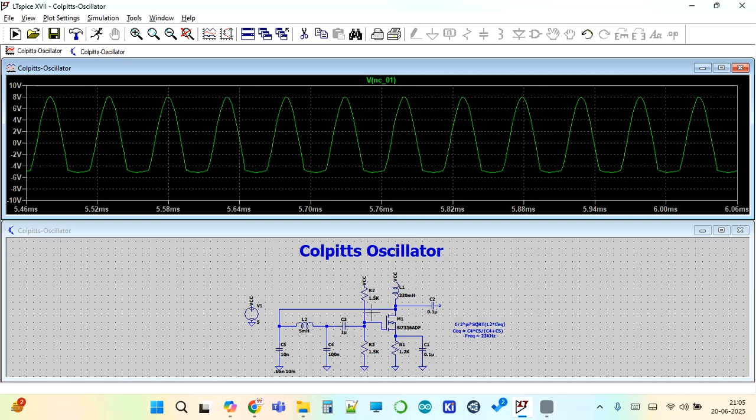One thing is, if you give 12 volts here, the resistive divider creates 6 volts. Ensure that you don't exceed the VGS too much, but that it is above the VGS threshold. That's what we have to ensure.